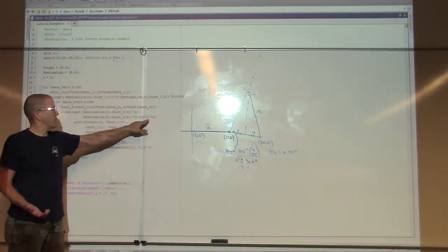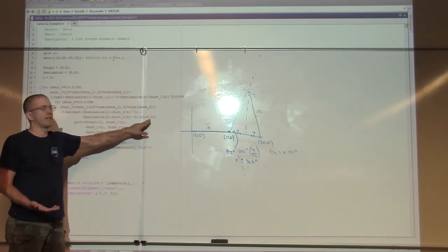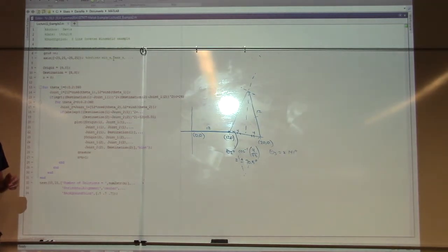In this case, this could be 0.01 inches or 0.01 millimeters or whatever the case is. This is just the maximum allowable deviation that we're allowing our robot to have, okay? So if it was millimeters, that would mean we were allowing 10 microns of variation between the desired destination and the actual destination. That makes sense?